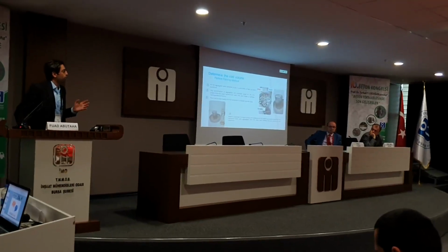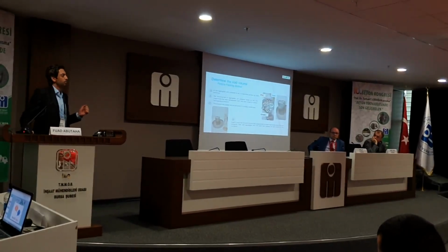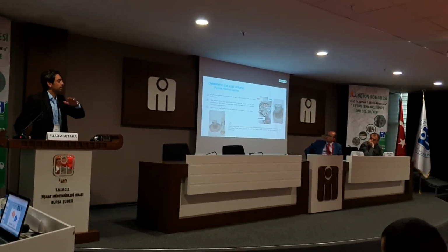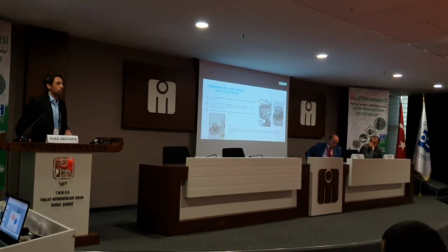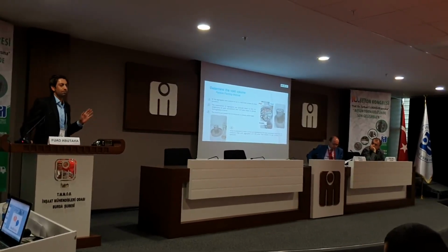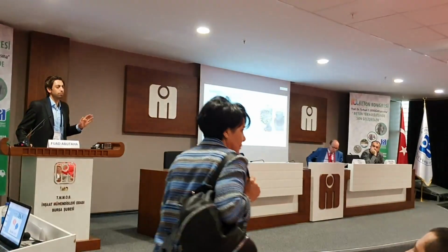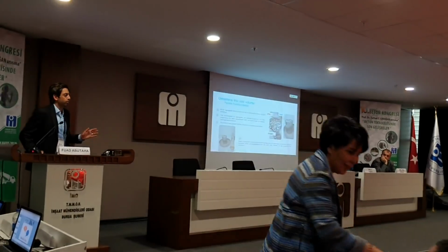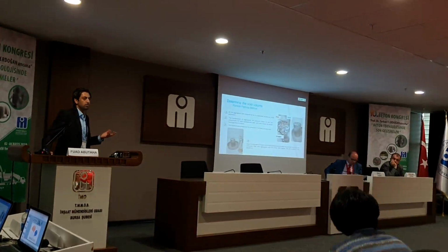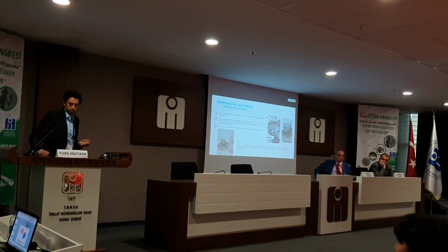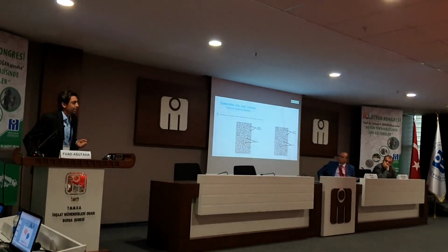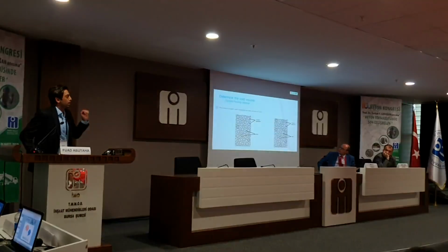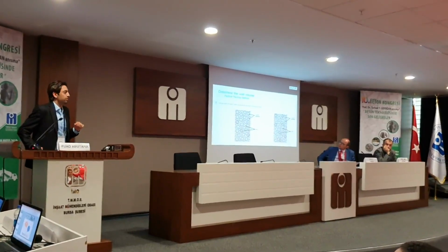Then a known volume of water was prepared, and subsequently the water was poured into the container until it reached the top. This process was conducted for each replacement level of POC, from 20, 40, 60 up to full replacement, to measure the void volume in the mixtures. Lastly, the amount of water used for each replacement level represents the total voids in the mixtures.